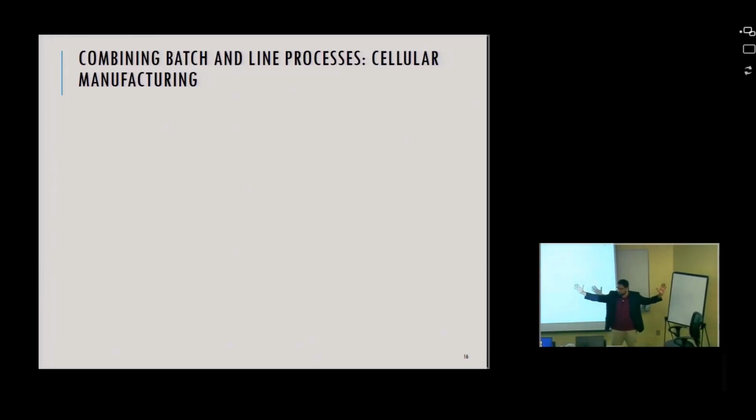to take a job shop and make assembly lines in the job shop. So this is a job shop that makes 100 products. So you have this big variety, big range. They will group the products based on not customers, not color or size, but based on processing requirements. So if this product requires certain steps and these 10 products require the same steps, we'll club them into one family or group. So instead of having 100 different products, taking 100 different paths through your factory, you make 10 groups so that the 10 groups may take different paths, but each group has about the same path.